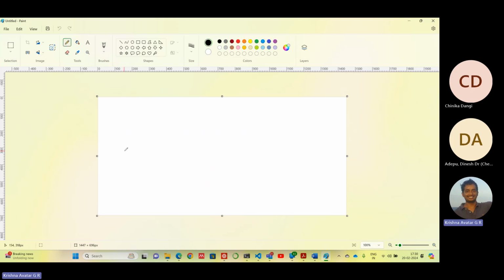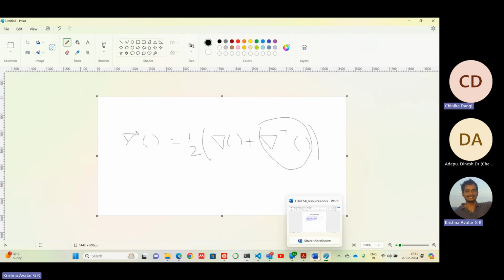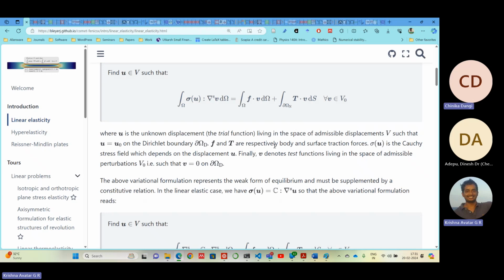So in this case, what we are essentially doing is grad S as an operator is equal to half of the grad operator plus the grad transpose operator. So this grad transpose happens to be nonlinear. I have seen people calling it that because it complicates things a bit. Grad transpose is something which essentially involves coupling between terms. We'll discuss this sometime later.